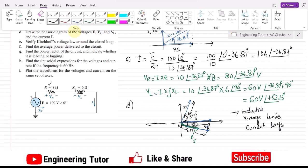Okay. Similarly, we will also find the value of the power factor. As the current is lagging here, the power factor will also lag, because the power factor of any circuit is related to the current. Whether the current is lagging or leading, the power factor will also be lagging or leading in that circuit. So that is the phasor diagram of this circuit.